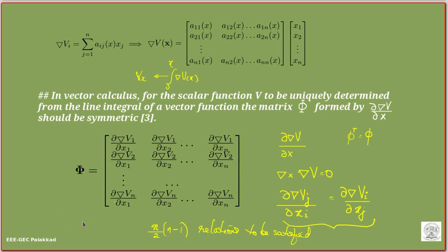That means we will also find out V dot. What is V dot? V dot is equal to dou V by dou x into x dot. We will apply this, and we will impose a condition that the coefficients of this have to be negative definite. So V dot of x has to be negative definite for the system to be stable, and then we choose the coefficients, and finally we go and check V, and see whether V is a positive definite function. Okay, so this is the idea of the variable gradient method.